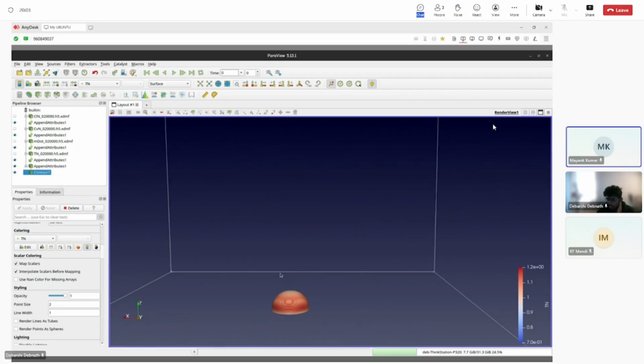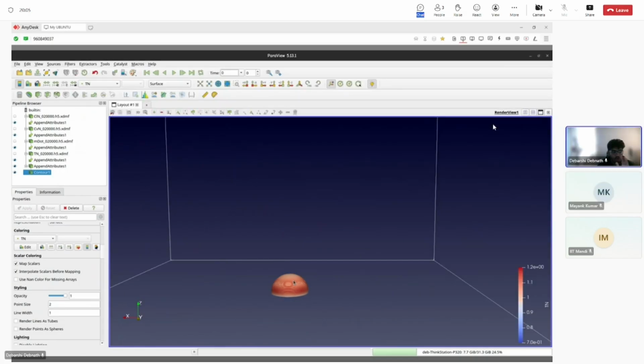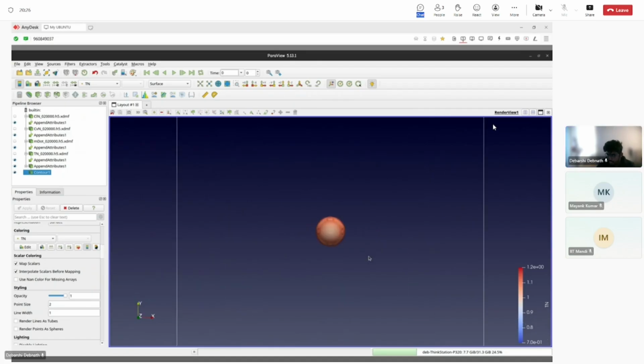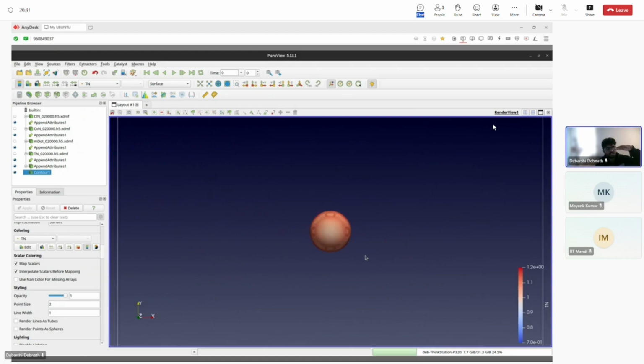So if you see the temperature contour on the droplet interface, it also has a gradient because of the evaporation, because of the evaporative cooling. As you saw, the evaporation is a bit faster near the periphery of the droplet. If we go to the top view again, since our droplet is placed on a surface which is heated, the temperature on the surface is higher.